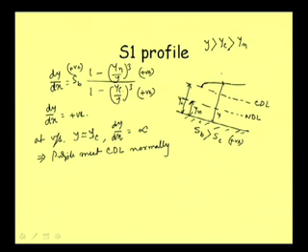Of course, we are just discussing the characteristics of the S1 profile, and in nature it is not that flow is coming on the critical depth line and jumping like that. Basically, it will be coming on the normal depth line. Without any obstruction or barrier, the flow will always tend to move with normal depth.